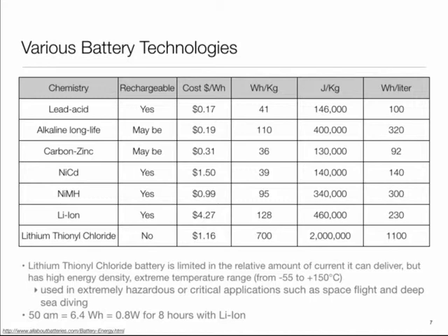So very broadly then: rechargeable, non-rechargeable, and within that what the energy density is, both in terms of mass and volume, and what the current density is, which I don't have out here. But actually, one of the reasons nickel cadmium or NiCads remained around for a long while is in applications such as remote control cars and all, because NiCads have very good power density. That is, they can give out a lot of high current basically. So it took a time before some of those applications migrated.